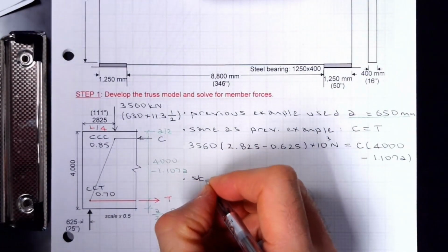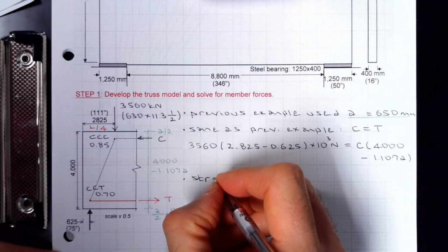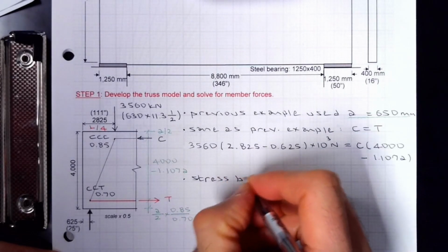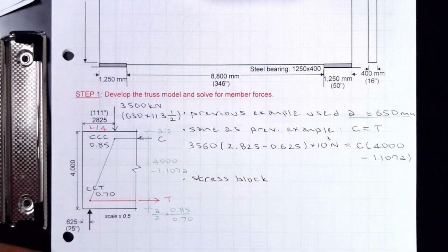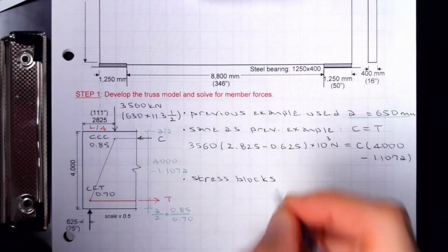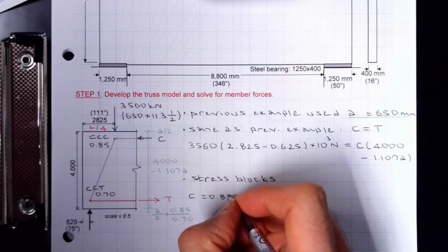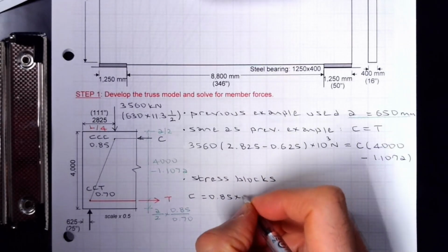And then I remember strength of materials from undergraduate studies. Stress blocks. You use this very often for any single design using sectional method. So using stress blocks, compression would be the same as, there's a coefficient which is 0.85.